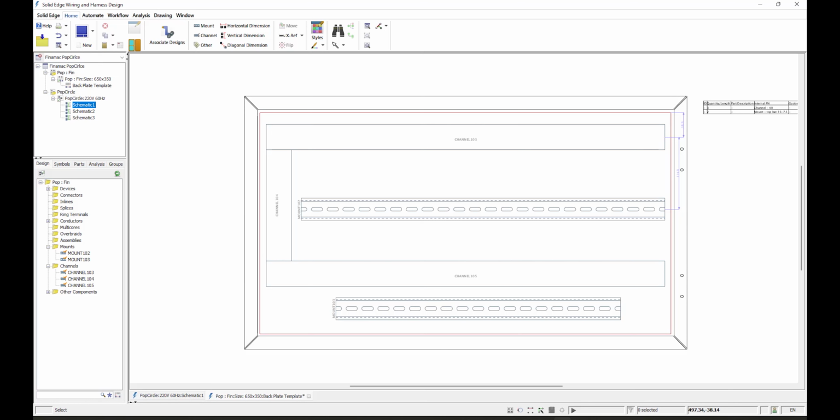What I'm going to look for is on the design part right here on the devices. You can see there are unplaced devices there, and obviously there they are right there. And what I'm going to do now on the group side here, you can see there's zones, right? So those are what are not placed yet. I need to go ahead and drag these into my specific zone here. So that's what I'm going to do.